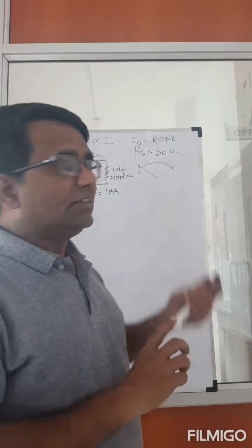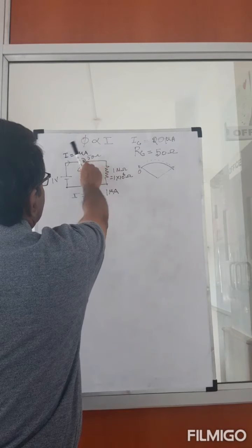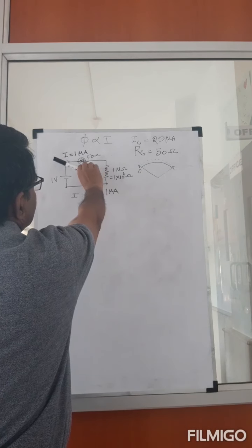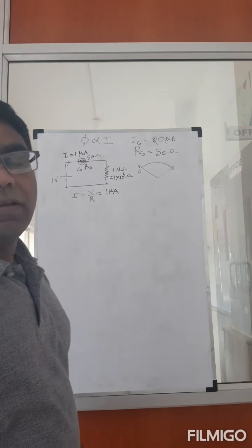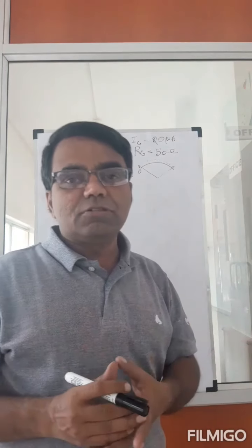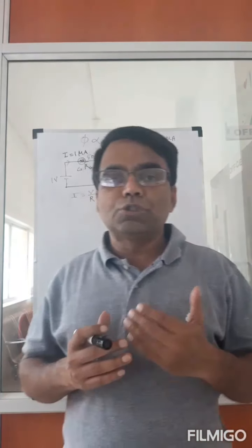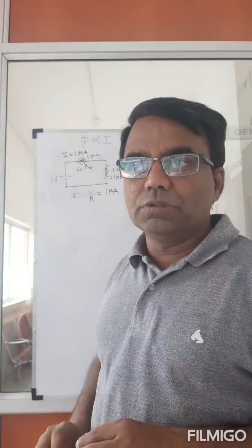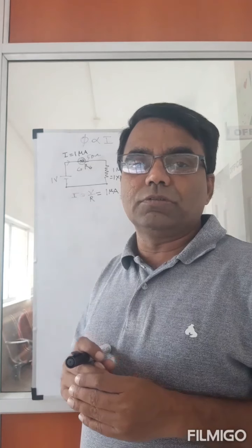But one advantage of connecting this galvanometer there now is that it will show you the reading directly. It will show you a 5% deflection, and then you can read it. So you are using it as an ammeter. What is an ammeter? An ammeter is an instrument that allows you to measure the current flowing through the circuit. So the galvanometer can be used as an ammeter now for currents which are very, very small in amount.